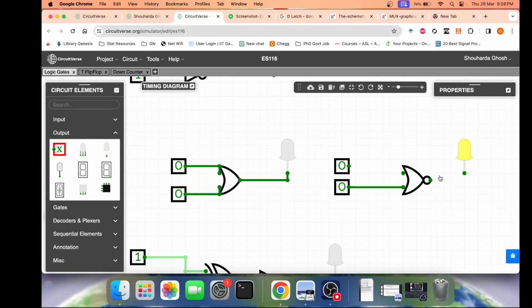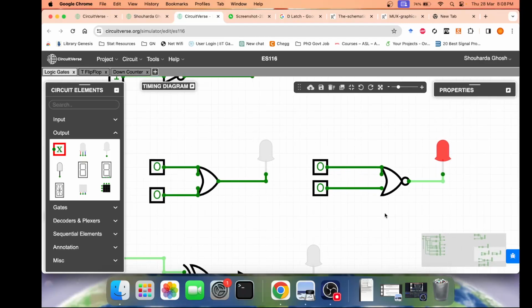And so as you can see very well, the OR gate is 0 only when all the inputs are 0. So what do I expect a NOR gate to behave like? A NOR gate will give me 1 when all the inputs are 0, as you can see.